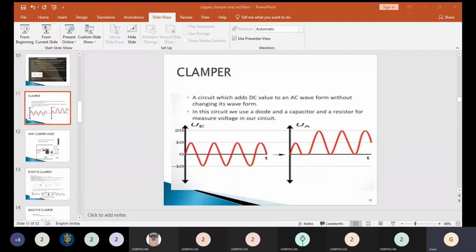Less expensive: full wave rectifier with 4 diodes. In a bridge rectifier, we use a normal step-up or step-down transformer. But in the center-tapped full wave rectifier, it is bulky and costly. Why is its implementation costly? Tapping at the center is very difficult compared with a normal transformer. So cost-wise, implementation-wise and size-wise, everything is complicated. So less expensive transformer is correct.